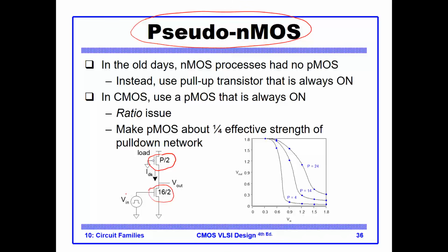So that's my input here, which is Vn. Vn is not fed to the PMOS because the PMOS is just a single transistor with its gate connected to ground. So it is on all the time. I like to call it always on. Okay, very interesting design.